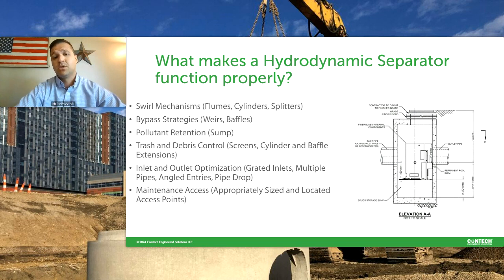So we have the ability to not only treat water, but bypass that 10-year, that 25-year, the 50-year storm event. With that, oftentimes that's going to be dictated by the weir height, by a baffle height that you have within that structure itself. Ultimately, the goal with being able to accommodate bypass is, can we take that 50-year storm event and make sure everything's retained within our system while from those previously ran storm events?